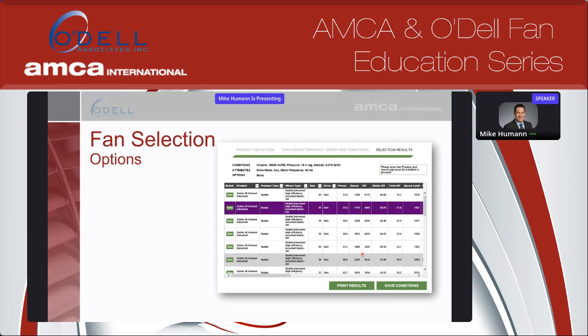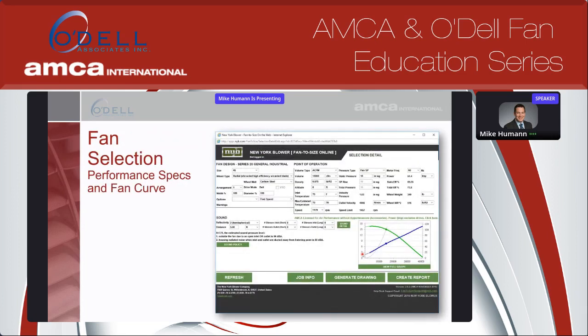And once you make that actual selection, you get a fan curve. The nice thing about this curve is, if you do have a special density or non-standard air, this curve takes that into consideration versus what you see in a bulletin. Most fan manufacturers have software or online programs to help you with your fan selection. You see your fan curve, and it gives you a lot of details about the efficiency of the fan, your outlet velocity, and some of the other details you'll need to know for your system.